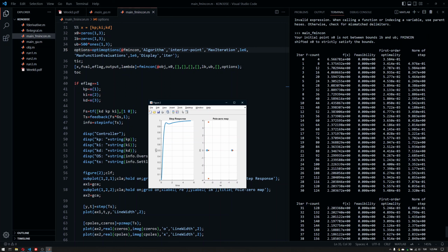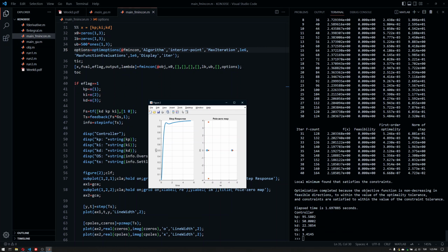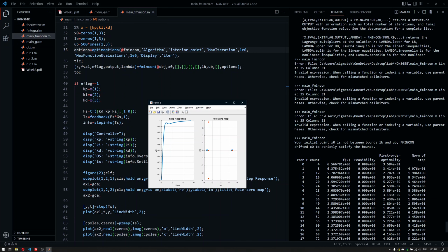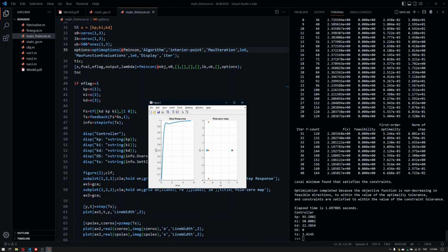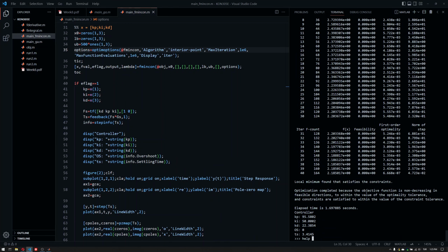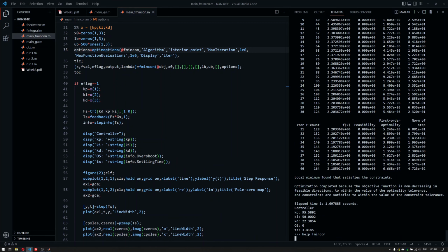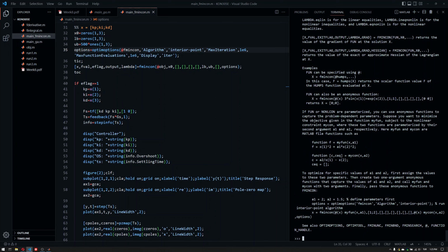And at this stage, you should be able to just run them maybe, and then get the idea behind the FMINCON, what it is doing, what maybe GA is doing. By the way, there's also lots of other functions. So help, FMINCON, it's not only minimization. You have actually fminsearch and stuff like that. So if you look at the documentation, you can just go with that. You can also use the Optim tools. It's a tool on its own, so I'm not really covering that part. So you can just check it out on your own.